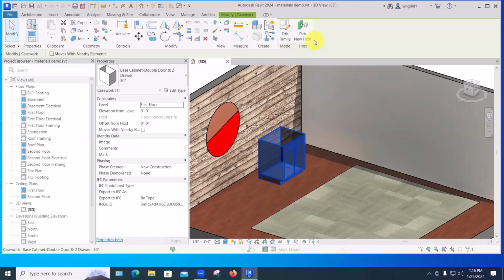So Revit provides a very handy way to assign materials to all or part of a component, to individual instances of a type, or to all instances of a type. And this is all done from the project level, not having to go back into Edit Family. You can change it for the whole object, or for part of an object. You can have the legs of a table be chrome or black, while at the same time deciding whether the top of the table is wood or glass, something like that. So we're going to work through just how that works.